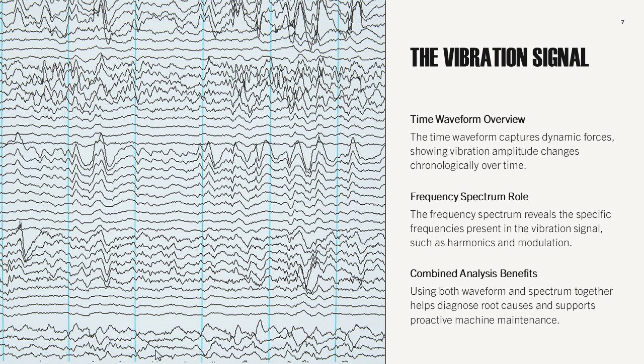Analysts often use both views together, the waveform to detect irregularities and the spectrum to pinpoint their frequency components. This combined approach ensures a thorough understanding of machine condition and supports proactive maintenance strategies.